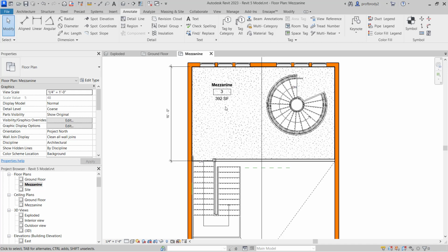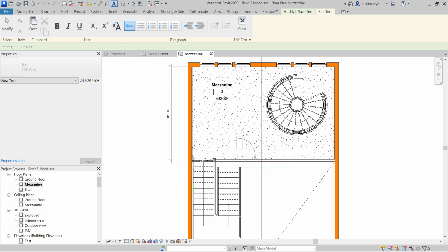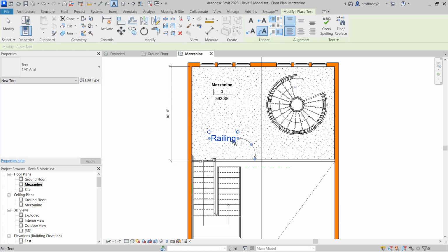And notes are a great way to help when your drawing is not entirely clear on what's going on. You can just add in notes to help explain things. For example, if I click the text tool, right now it's set over here to just show me text. However, I can add a leader line, and that leader line can have one segment, it can have two segments, and it can be curvy if you're just feeling like you really want to have a great day. And the curvy one, you can see here, it kind of auto-generates the curve based on where you place the text, and I can add in some information that may not be entirely clear just from the drawing.